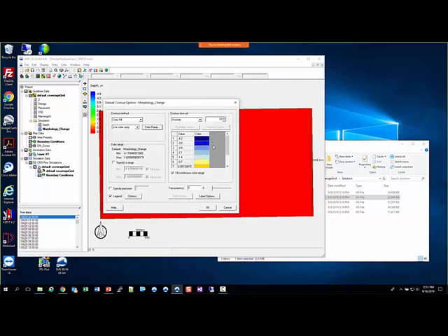For that color ramp, it's easier to see. You notice there's no white in here. It's easier to see the areas of zero change if you have an odd number. And we also need to make the range a symmetric range. So let's go to -4 to 4. And then you can change these values as you need to make it show up a little bit easier.